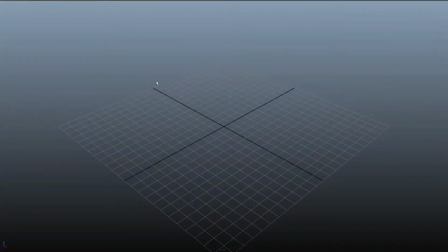Okay, now that you have your 3D modeling program of choice open, first thing to do, simply make a plane. And we're going to be working exclusively in polygons. We're not going to be using any curves, no NURBs, no splines, straight up polygons to make everything so simple and so easy and so straightforward, and it makes everything much easier to manage and to modify later. So just create a plane in Z, and that's if Y is up.